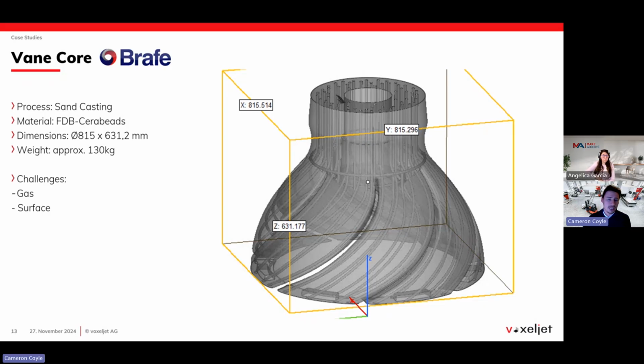So what you can see in the image in a transparent view is the customer worked to actually create some venting pipes all the way through the core in many areas in the vanes. And there's also additional parts that make up the core package. And all of these venting holes align with the next core underneath it or above it in order to direct the gas out of the mold. So that's really supporting that particular customer a lot to reduce those issues.